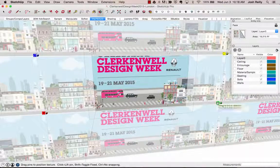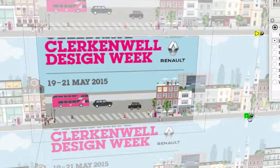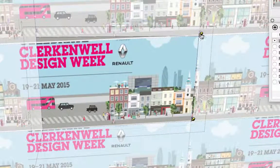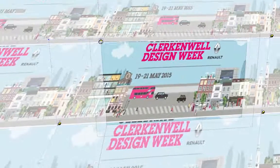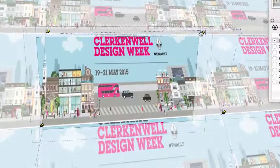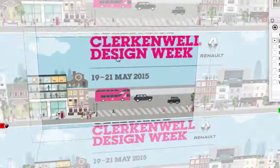And here I'm holding down the Shift key. Actually it's a toggle. You can just tap the Shift key and you can get these fixed pins or use these colored pins. So the fixed pins let you click and drag almost like you're pinning up a poster. So this is keeping the location of the pin in relation to the image fixed and letting you pull that to a corner of the model. So you can kind of snap to geometry. Just make sure you're clicking right on that pin. Sometimes it skews it a little bit, so you may not want this option. So I'm going to undo that and just go back here and simply click and drag to put it where I want.